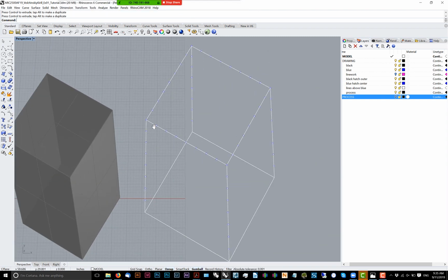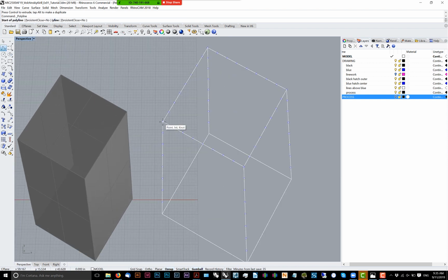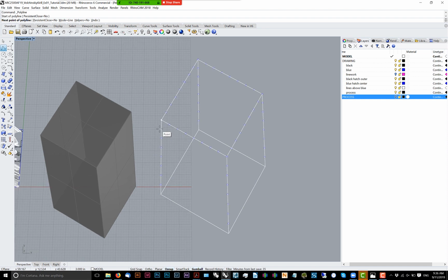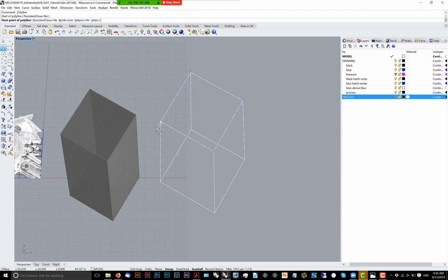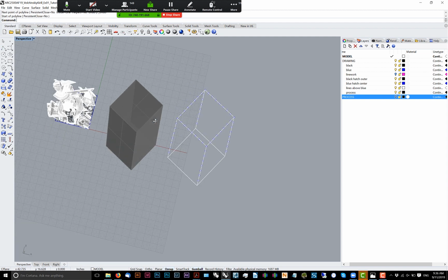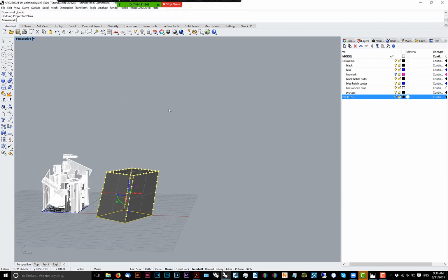What's interesting is that if you measure the distances, these are each 3 inches. So in plan, you actually don't distort your drawing whatsoever. And the same goes for elevation. So this axonometry preserves the dimensions entirely. Contrary to a perspectival projection, where obviously these distances decrease, in an axon they stay true.